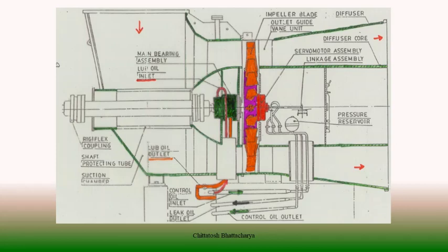Unlike radial fans, in axial fans, particularly in AP fans, we have axial blade pitch control. This is the arrangement which ensures that we can control the flow of gaseous fluid within the fan impeller itself. In case of radial fans, impellers are fixed, but in AP-type fans, the impellers can be tilted with the axial blade pitch control arrangement. We can tilt them up to 60 degrees in 16 divisions, and that way we can control the quantity of gaseous fluid flow across the fan. So this is an additional feature along with damper control, inlet dampers and outlet dampers.